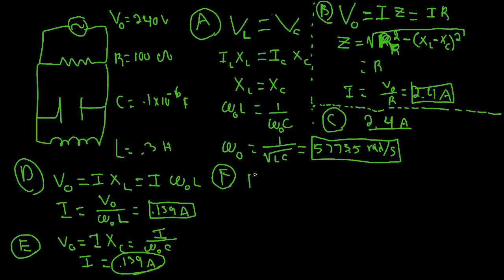So let's start with the easier one. We know that the energy stored in the capacitor is equal to 1/2 times the capacitance times the voltage across the plates squared. Since they want the maximum energy stored in it, that's only going to happen when the electric field between the plates is maximum, and that only happens when there's a maximum voltage. And so we're going to put that V naught to show that we're going to use the maximum voltage, which was stated in the question, actually. And so we have the capacitance, we have the maximum voltage, and so all of that will turn out to be 0.0029 joules, or more appropriately, we can say 2.9 millijoules.